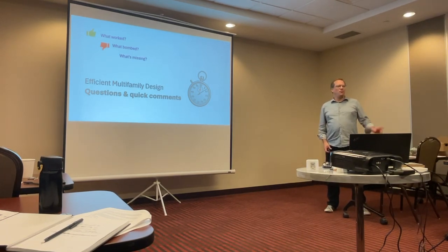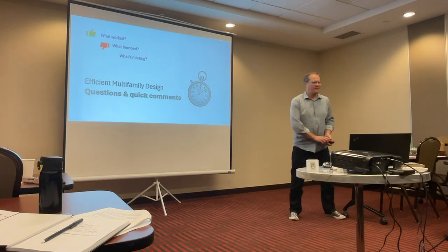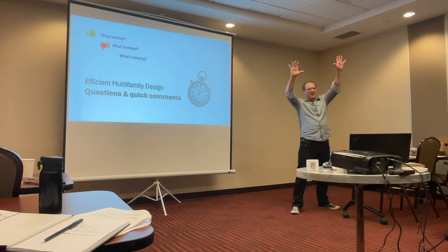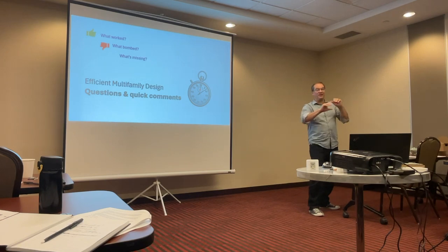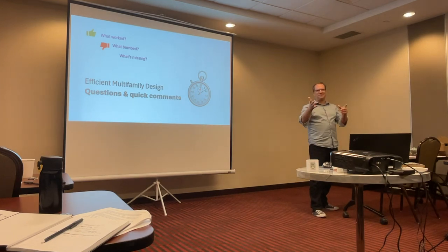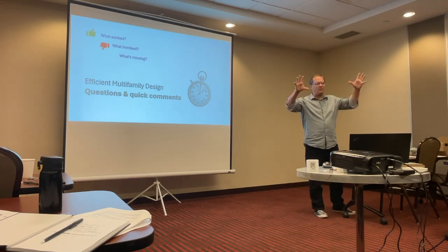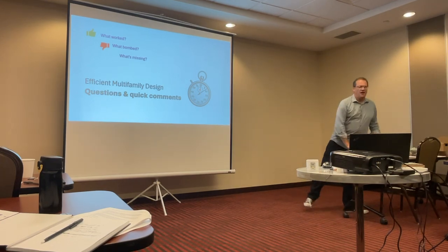Do you want to know the one sentence of truth that the RDH has made millions and millions on over the years? All those big buildings, you have hanging glass and you have standing glass. Guess where it leaks? Right where the hanging and standing glass meet. We've been selling that advice over and over again, making millions just saying what I just said. You're right, it's where things shift that they always break down and leak. That is 100% predictable.